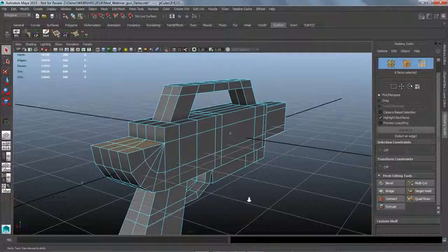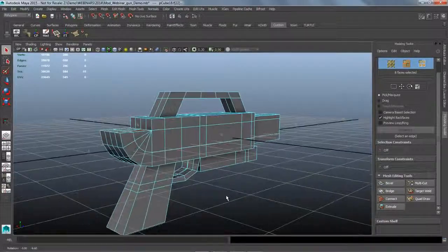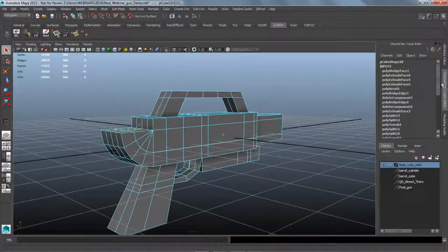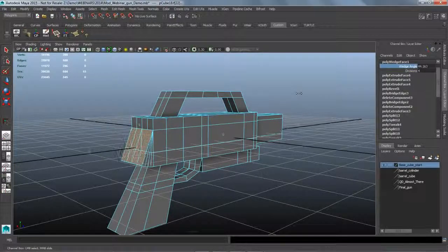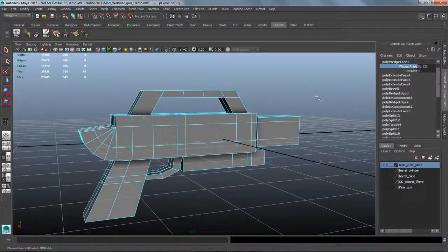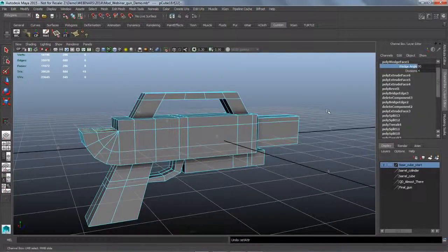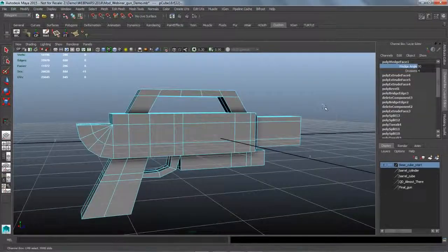So if I just hit wedge, it's going to dial in this kind of nice effect for me here so that I can set the overall degree that I want to work on, that wedge angle, and how many divisions I want to have. So you're getting this nice way of sweeping a nice effect across there. And that's just because I grabbed several faces and then defined the edges that I want to sweep that overall effect around in there.